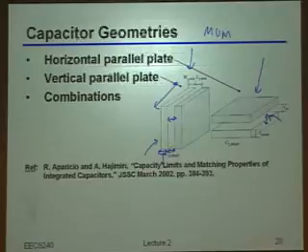In fact, they'll start playing games where they'll screw around with the dielectric properties of the so-called intralayer dielectric versus the interlayer dielectric. In many cases, to the extent that they could, they would be totally happy to make the capacitance between the layers, for all intents and purposes, 0, right? Because, hey, it doesn't buy them anything. It's just extra cap, nothing else is useful there.